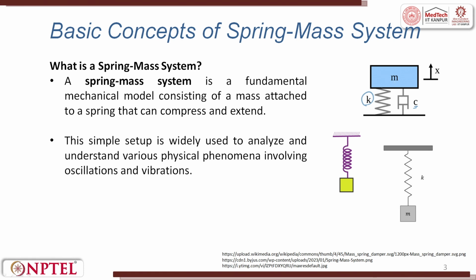You can use the mass also in the downward fashion, where it is used in a spring balance. For example, to measure weight 0 to 5 kgs, 0 to 15 kgs, you can also have 0 to 50 kgs. More the weight, lesser will be the resolution. So, you can have a spring attached to a mass. Now, here you will see a graduation. Based on the graduation, you can figure out what the weight in kgs is.